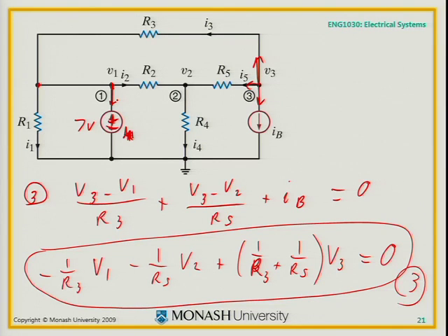But if you blindly tried to apply KCL at every node again, then it wouldn't work. And so that's one trick to worry about. If there's a voltage source between ground and one of your nodes, you can immediately write down the value, the voltage of that node. You've already solved it. All right, that's great, that's good. We're doing next lecture now.